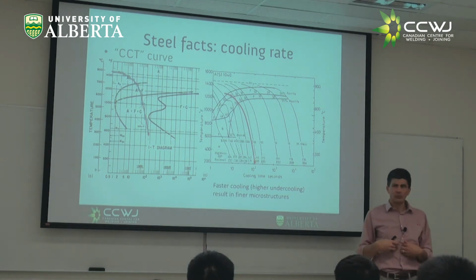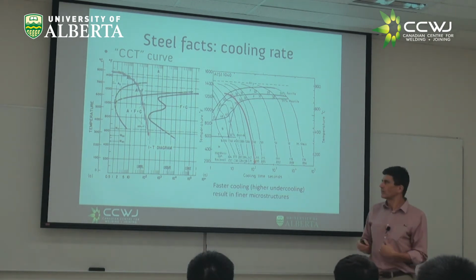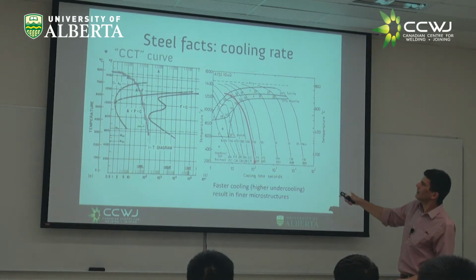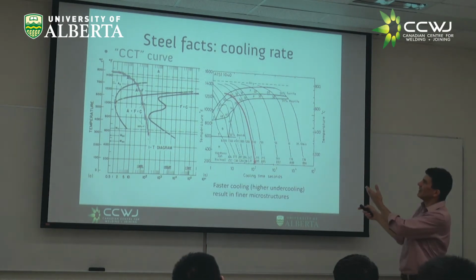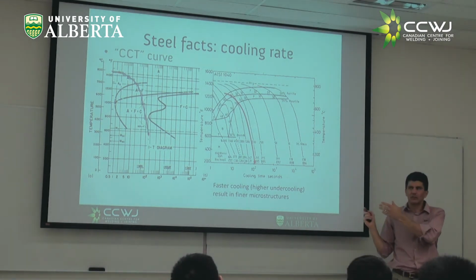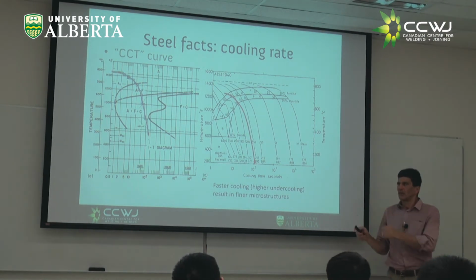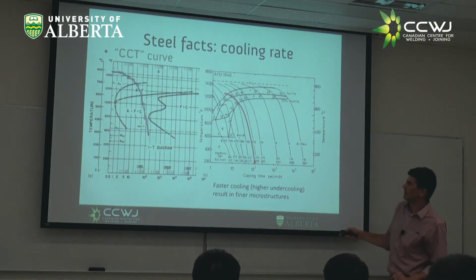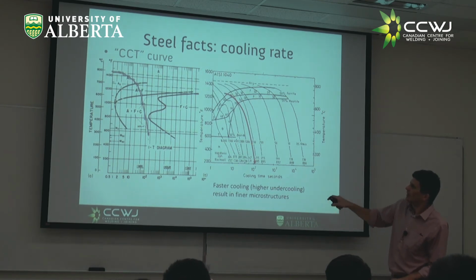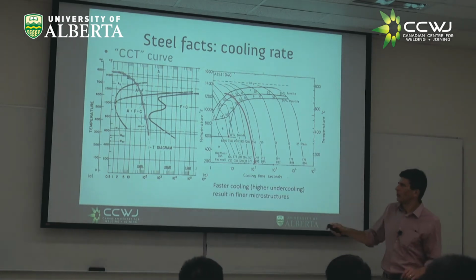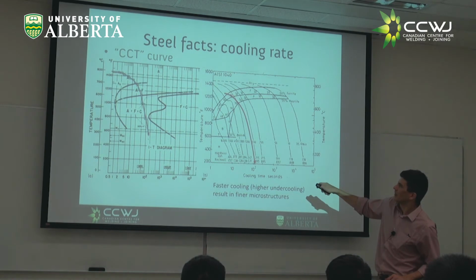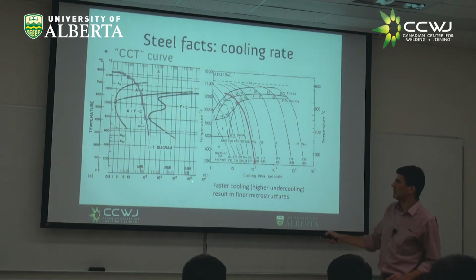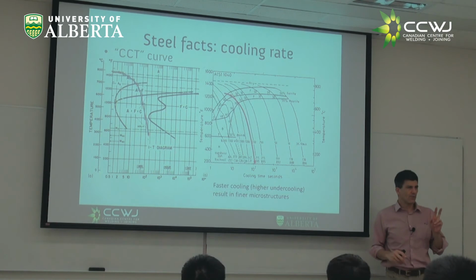The thing to do the experiment is a dilatometer, right? And then you get this other diagram. This is the CCT diagram, continuous cooling transformation diagram. And this is the TTT diagram, the time-temperature transformation diagram, which is isothermal holds. These two diagrams are very similar. Look, the vertical axis means temperature in both. The horizontal axis is time in log scale in both.